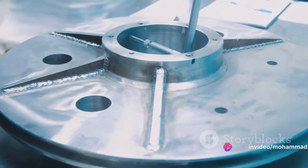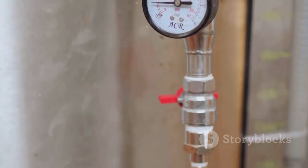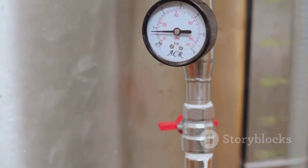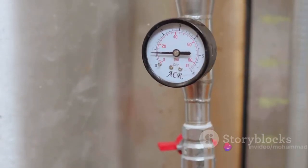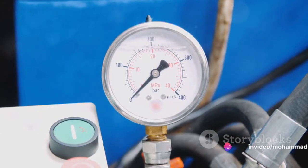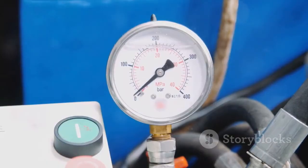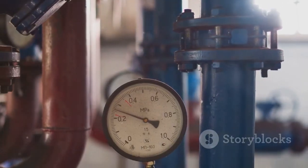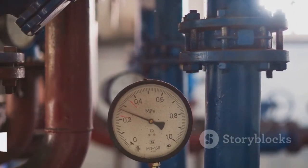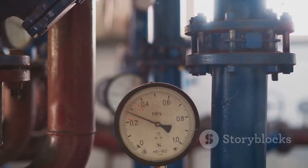This is where the Square Root Extractor comes into play. It's essential in applications like these because it extracts the square root of the differential pressure, making the flow rate directly proportional to this value. To put it simply, the Square Root Extractor is the mathematical magician that deciphers the flow rate measurement equation. And that's how you measure flow rate with a DP transmitter. It may seem complex at first, but once you understand the basics, it's a straightforward process.